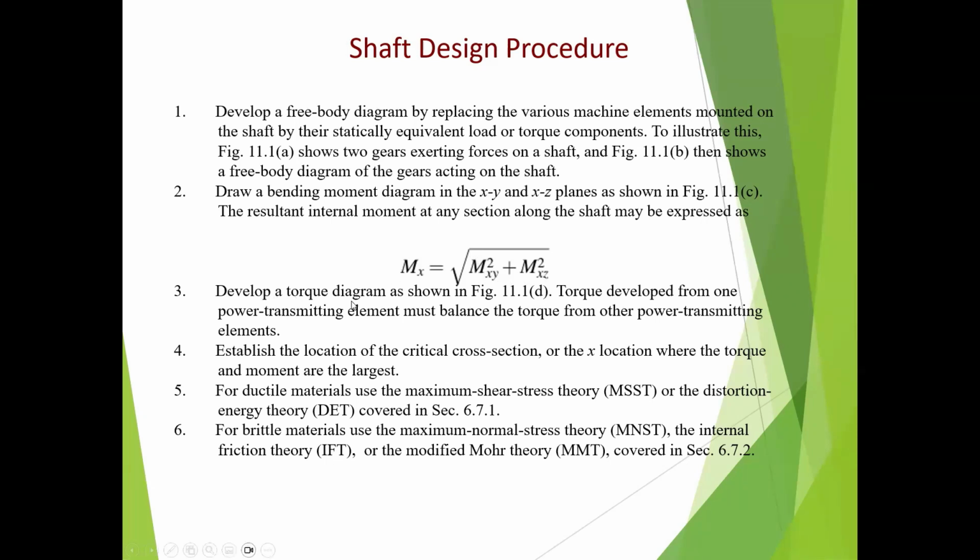Then develop a torque diagram, and the torque developed from one power transmitting element must balance the torque from other power transmitting elements. Establish the location of the critical cross section, or the x locations where the torque and moments are the largest.